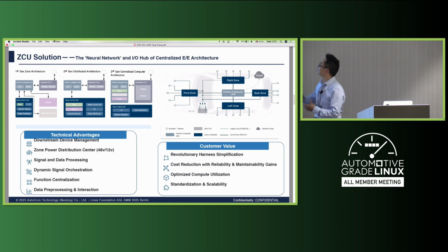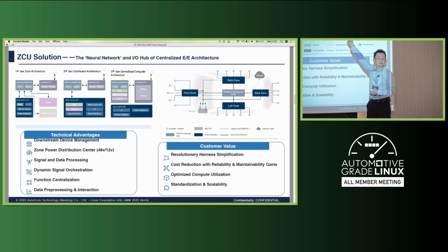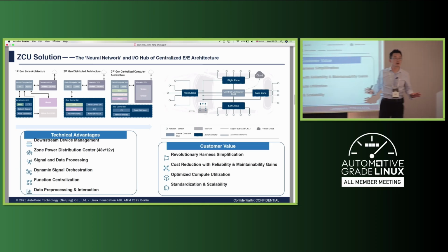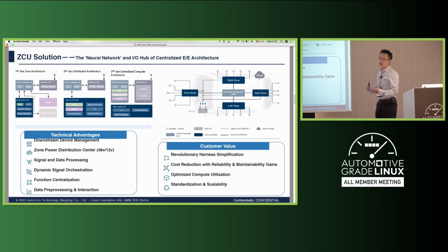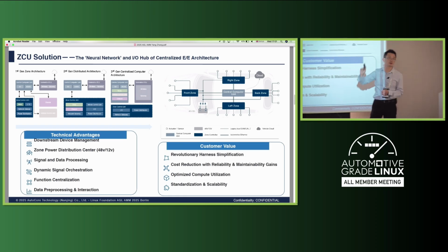What that means is, if any of the zonal controllers here failed, for example the back zone gets bumped or power is lost, what we have been able to achieve in the latest Q07 Chang'an SOP vehicle is that within 15 milliseconds, every task assigned or predefined on the back zone controller will be taken over by the rest of the controller system.